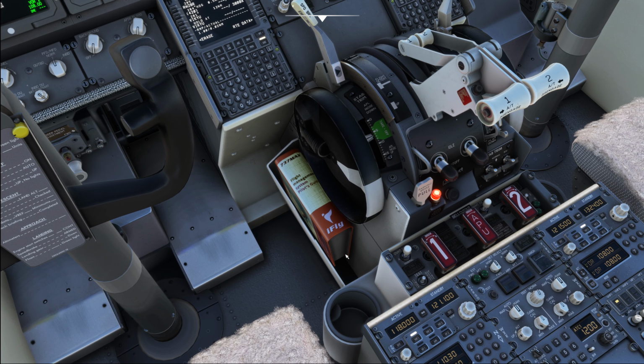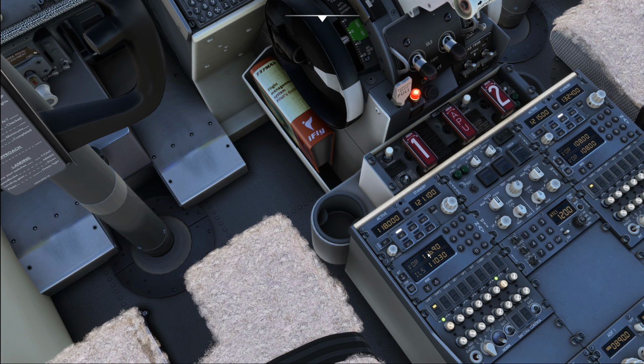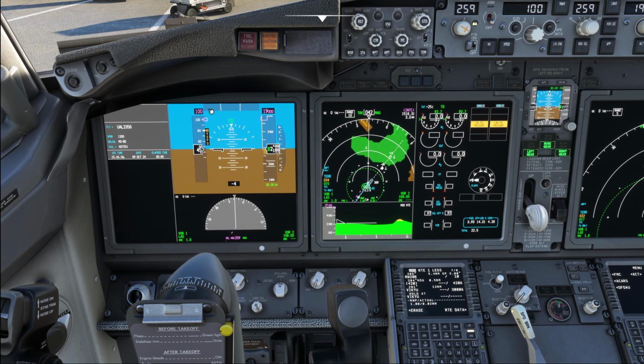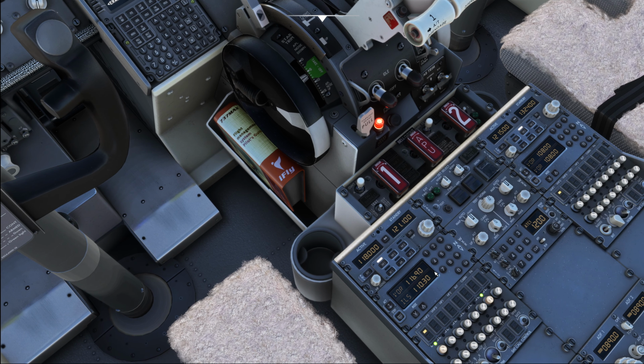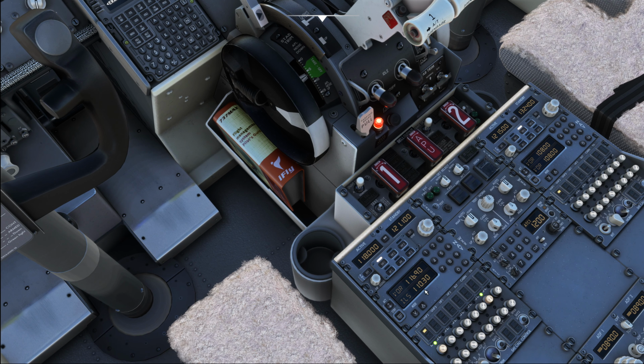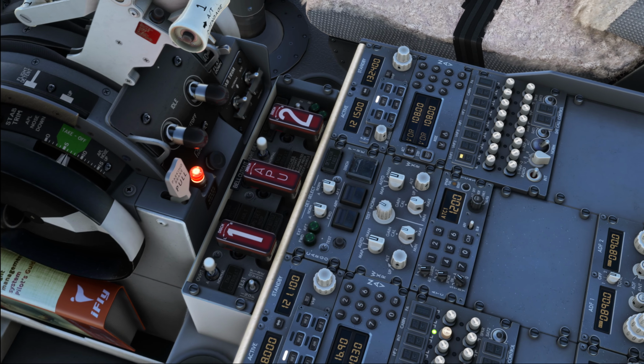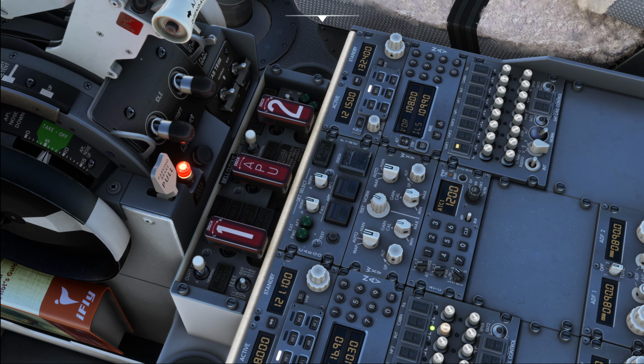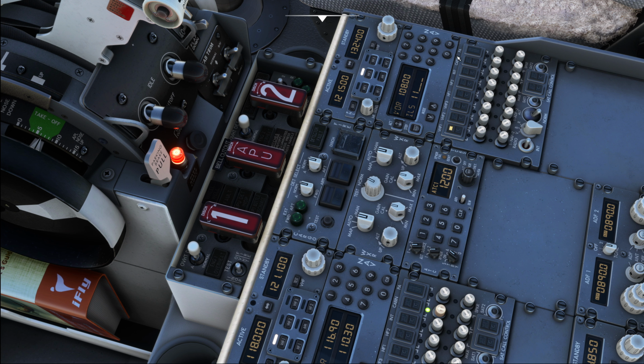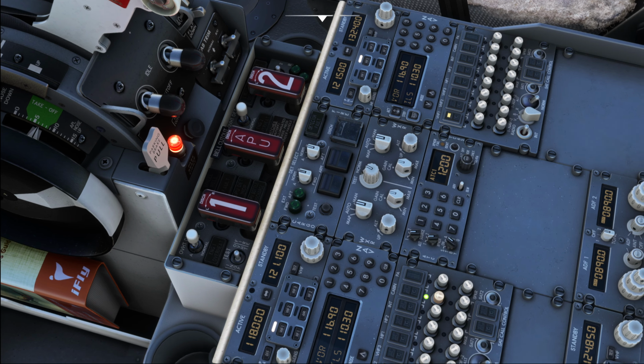Therefore, what I'm going to do is I will set the frequency of that Las Vegas VOR active so that our primary flight display is nice and clear, but we have the ILS frequency readily available in the bottom over here should we need it. And I'm going to do the same setup on the pilot monitoring side, so 110.3 going active and 116.9 for the VOR is now active as well.